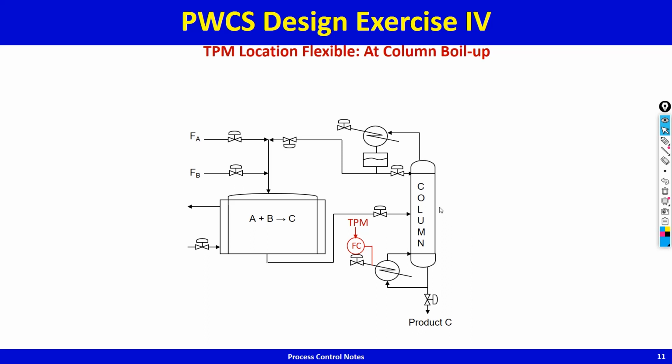Your distillate starts becoming impure, your bottom starts becoming impure. This entrainment flooding is because of too high a vapor rate, and that will be reflected as a large pressure drop across the column.